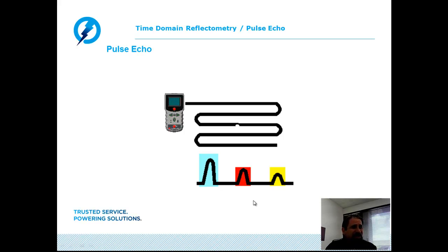be able to take measurements of cable length, and also the pulse echo technique is ideal for locating faults that are in series with the cable transmission path, such as a broken or open conductor or neutral. Severe corrosion building up on a concentric neutral can be found quite easily with a pulse echo technique. Separated splices or sealed off cable ends, etc. could be found relatively easily with a time domain reflectometer or pulse echo technique.